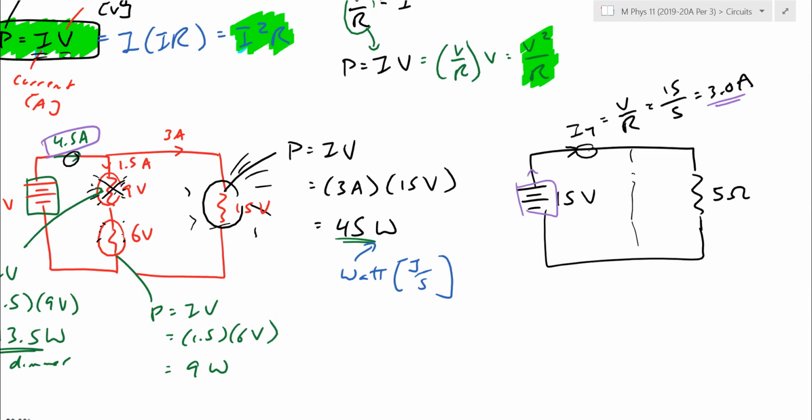I could do a similar analogy here. Let's say the other light bulb has burnt out. Because that parallel has burnt out, parallel paths usually decrease the total resistance. That's what actually made this overall current a little bit higher as a number. I would imagine if I just did that, if I burn out this path here, I'm just in series through just these 2 light bulbs here. These 2 light bulbs here are still burning really bright.